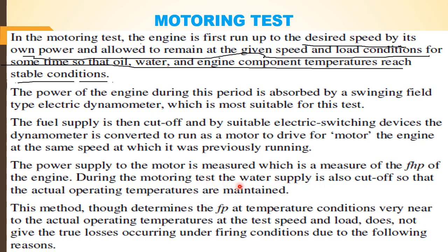During the motoring test, the water supply is also cut off, so that the actual operating temperatures are maintained. So this is a very important thing. We have to cut off the water supply also, so we try to maintain the original operating situation. So in this motoring test,